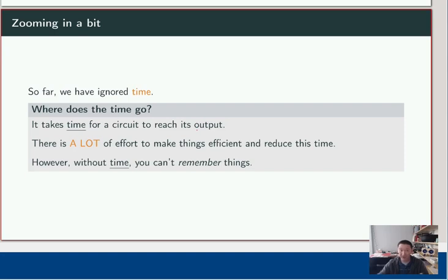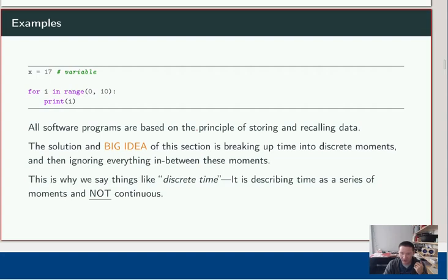And when you get into really serious chip design, trying to get billions and billions of these transistors all formed together on a single wafer, they all have to work in harmony, such that if you read a value, you can guarantee it's at the value it's supposed to be. It's not in a transition phase. That's a huge chunk of chip engineering and design, guaranteeing and verifying that all the paths and everything work out. Let me show you what I mean, since it might be a little confusing.